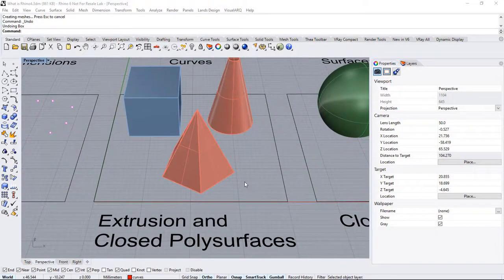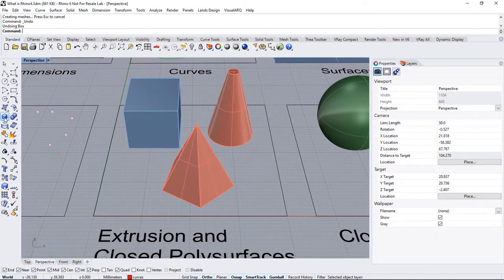We'll take a look at the tools to work with watertight solids. Under the box icon, you'll find some of the commands to create primitives such as cylinders, cones, or pyramids. Run any of these commands and make sure to follow the instructions in the command line. Don't forget to check the available options.